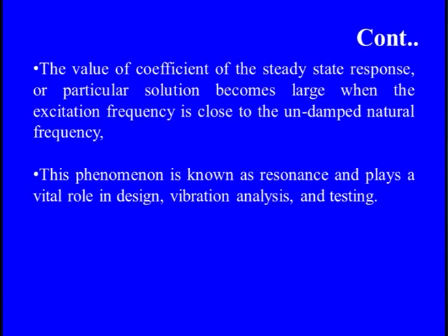And hence the term steady state response, which comes from the particular integral, is assigned to a particular solution, or we can say that the second term dominates the solution when we go for a large value of t. And the value of the coefficient for the steady state response, or particular solution, becomes very large when the exciting frequency is very close to the undamped natural frequency.